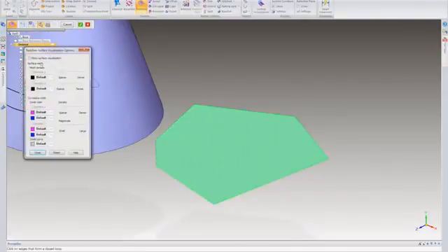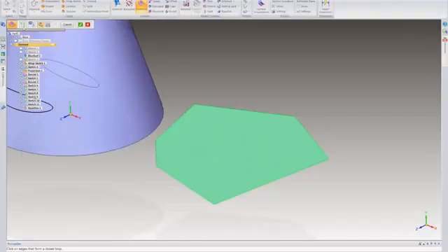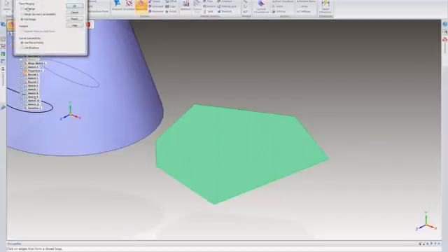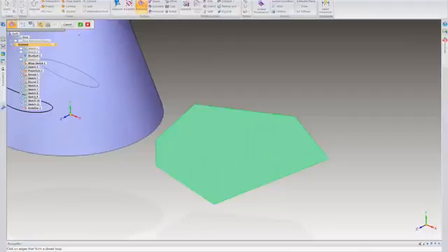Go back into the profile. All right, so we can say show surface visualization. Right now it's a flat piece of geometry. We can also come over here and say we want to merge as many surfaces as possible. So right now I have a full merge on. Sometimes when you start pulling and pushing on these and you start losing geometry, it will basically disconnect from that loose geometry and still maintain the surface. So I'm going to go ahead and maintain that.